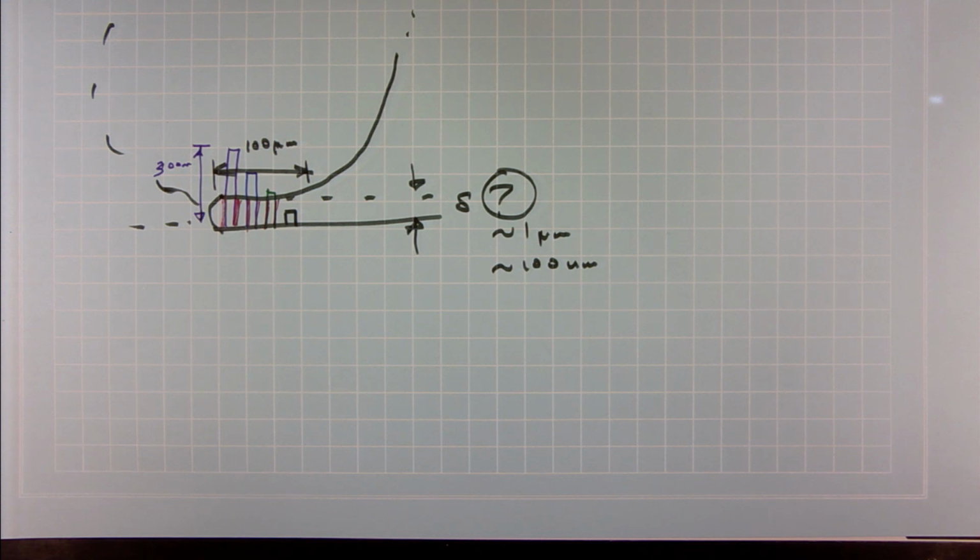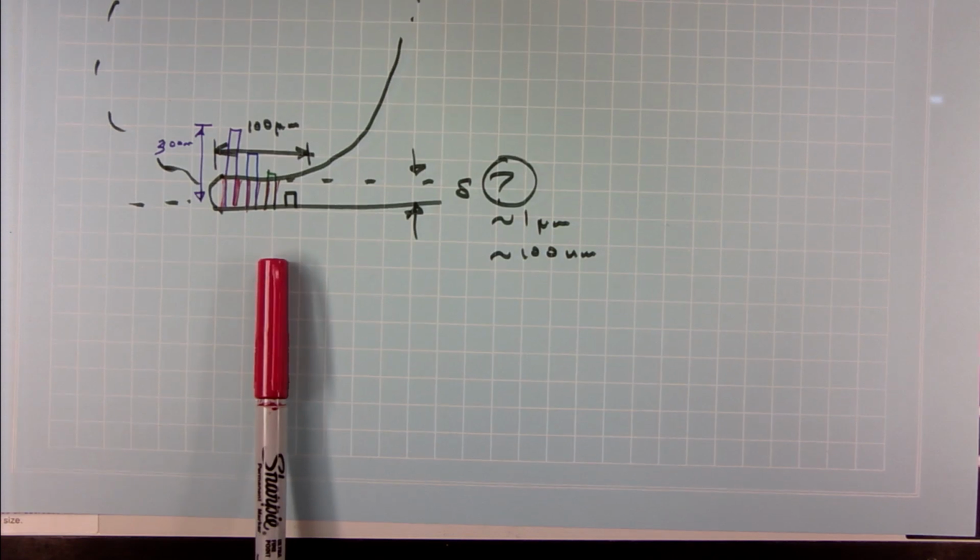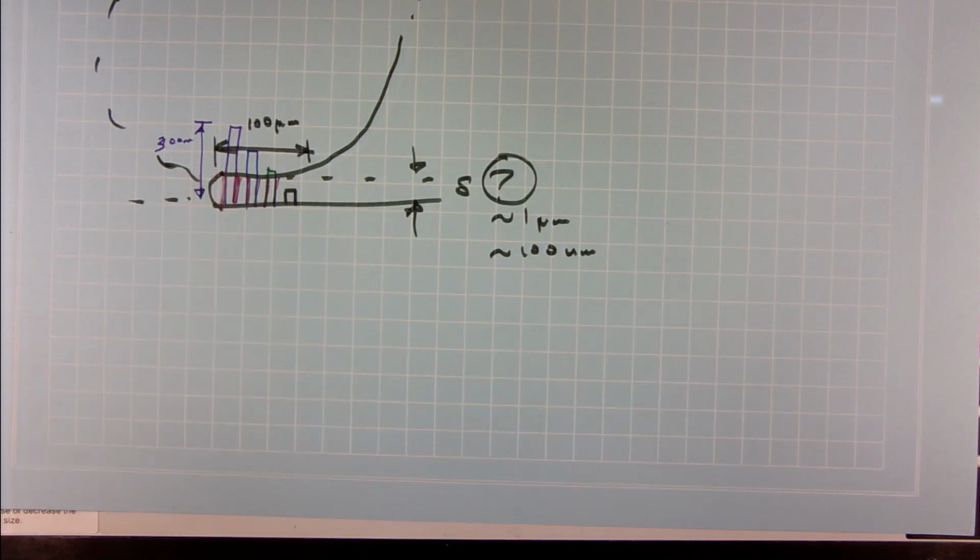This is a direct proof, okay, because optically I cannot measure it, it is below the wavelength of light. So, I cannot use interferometric techniques to go and measure the thickness. So, this is one way to prove that the micro layer is indeed 100 nanometers thick, because if it was more than 100 nanometers, then each of these fins would have given me different CHF. The fact that all of them are giving me the same CHF means only the first 100 nanometers of each of these fins is participating in the heat transfer, the rest of it is insulated,